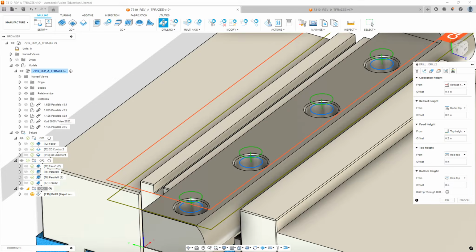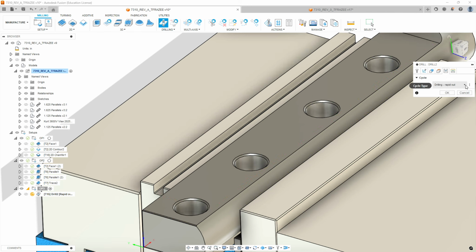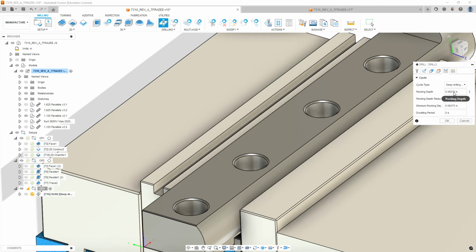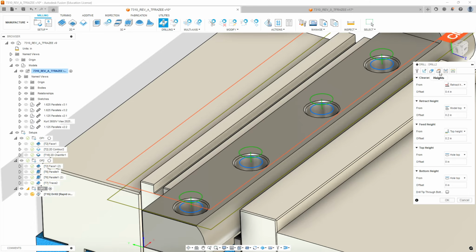Now let's look at what our peck depth is with this cutter. If we go to the deep drilling, it normally pecks at a 93 thousandths peck. So let's just do that. We're going to go back to drilling, and we're just going to do 1 peck on it, and we're going to go negative 0.093. Okay, and then we're going to get a little dimple there that our 1/2 inch drill bit will self-center on.